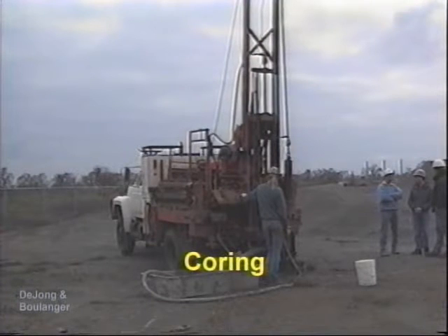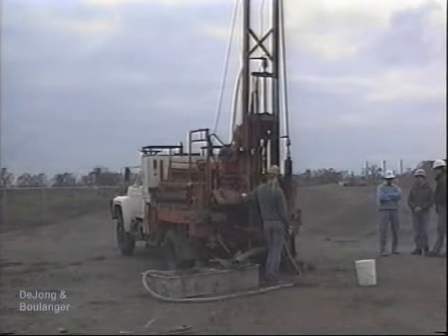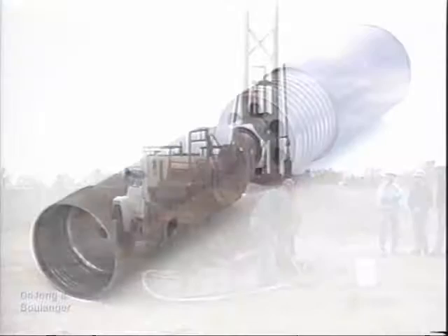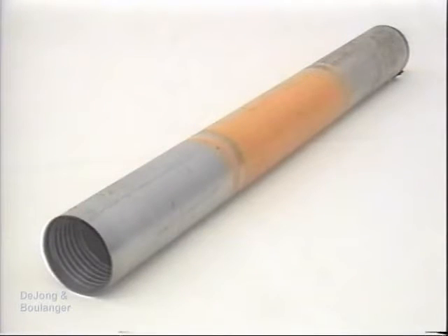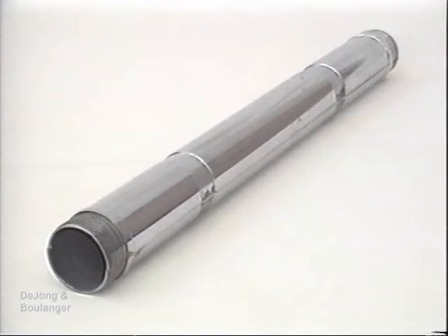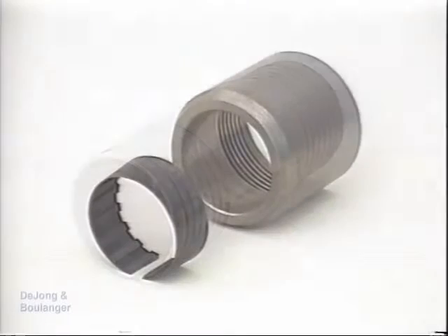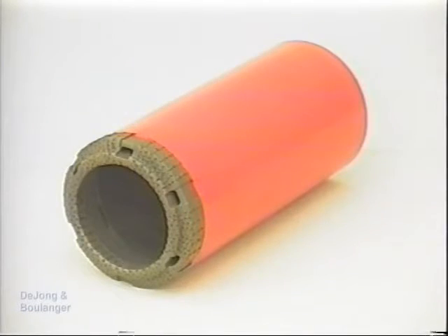Coring of rock or very hard soils is similar to mud rotary drilling, with the exception that sampling and drilling take place concurrently. To drill and sample simultaneously, a core barrel replaces the rotary bit at the end of the drill rods. The conventional core barrel is comprised of a core barrel head, an outer barrel, an inner core recovery tube, a reaming shell, a core lifter, and a coring bit.